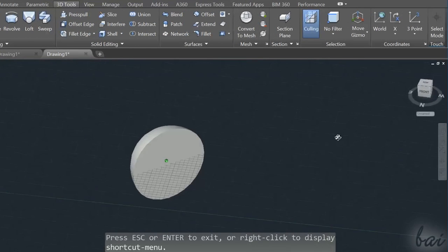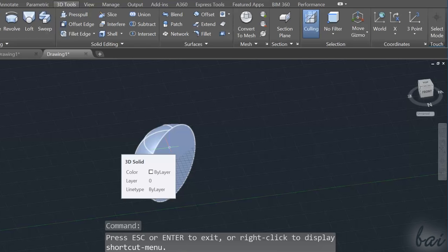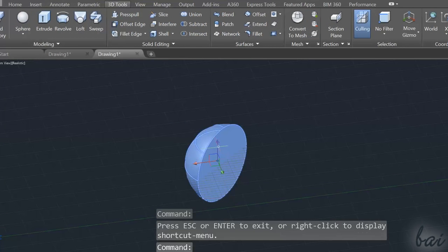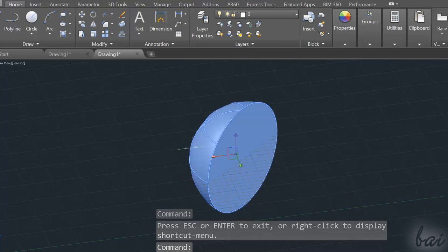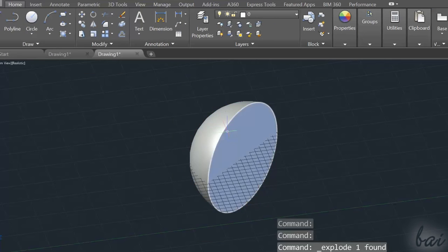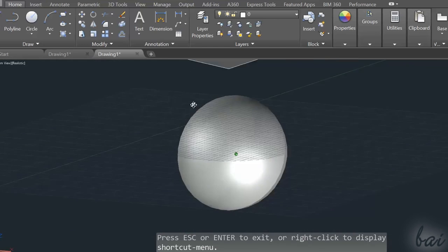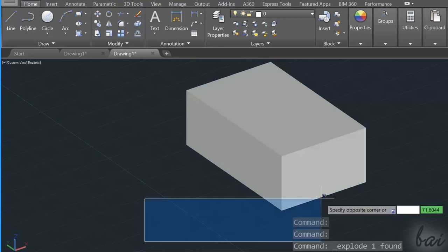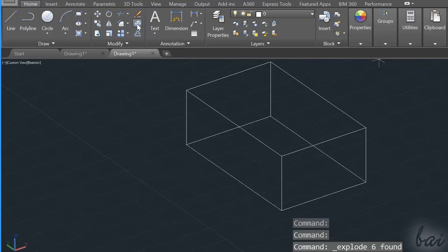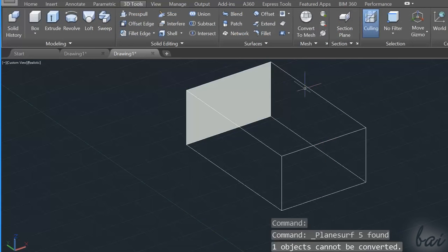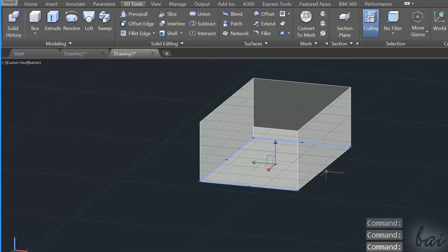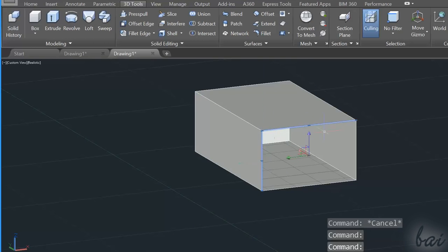You can extract surfaces from existing 3D objects by using the Explode command. If you start from curved solids, like cones and spheres, just select them and use the Explode command to extract all their surfaces. Whereas if you start from boxes composed of polygon faces, you'll have to explode the whole object twice in order to get all its lines and sides. Then, by using the Planar Surface tool, define all the face boundaries one by one, and then group all the surfaces together to manage them.